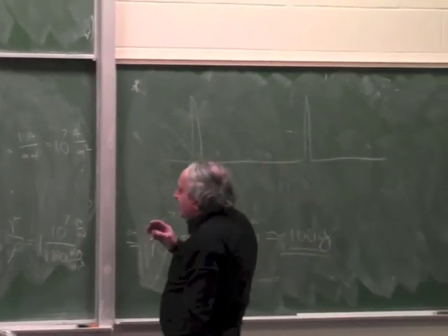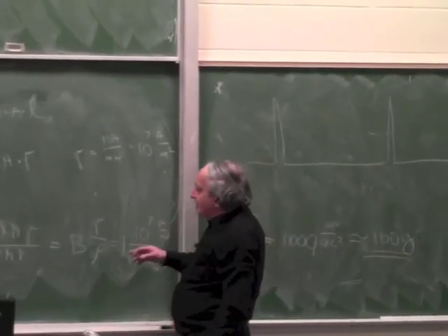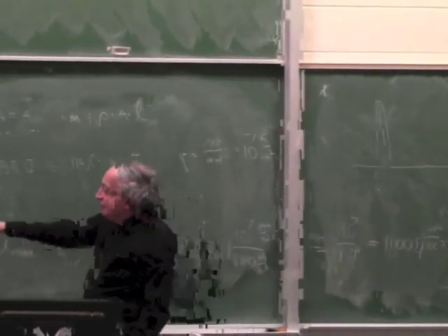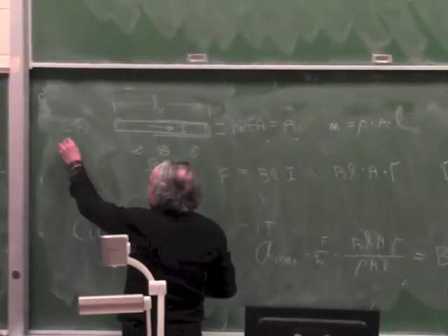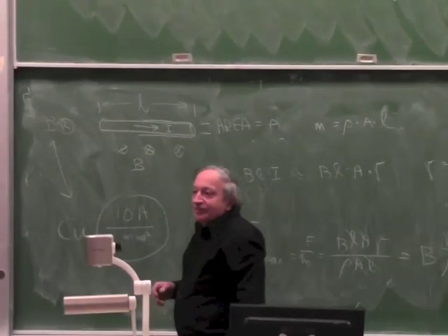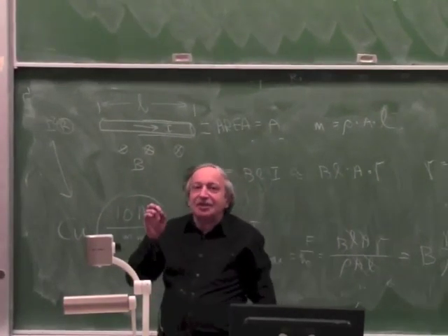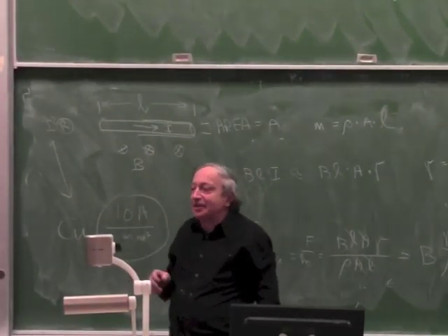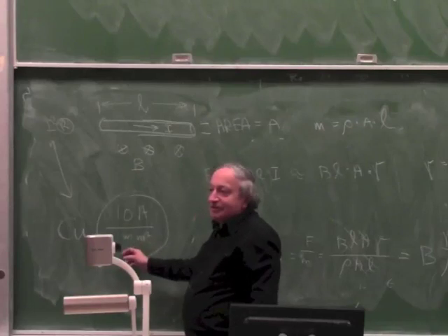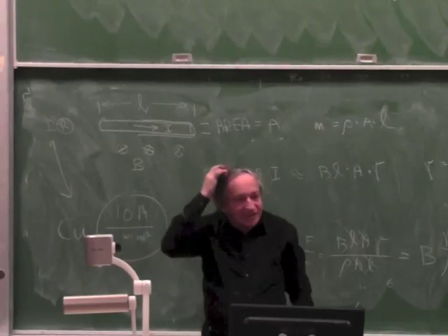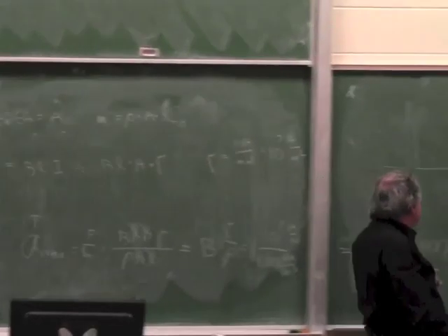But momentarily I can exceed this current by far, because this is because of heating, and if I only need to drive it infrequently with a pulse, I can greatly exceed this number. So this is a steady state limit.